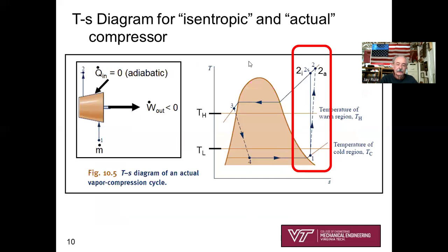The next thing you need to do is understand your compressor. What's given? Is the compressor given as reversible and adiabatic? In other words, the keyword ideal. If you read the words ideal refrigeration cycle, that means the compressor is reversible and adiabatic. Otherwise, you're going to look for compressor efficiency given to you, and that's going to determine the way you analyze the compressor process.